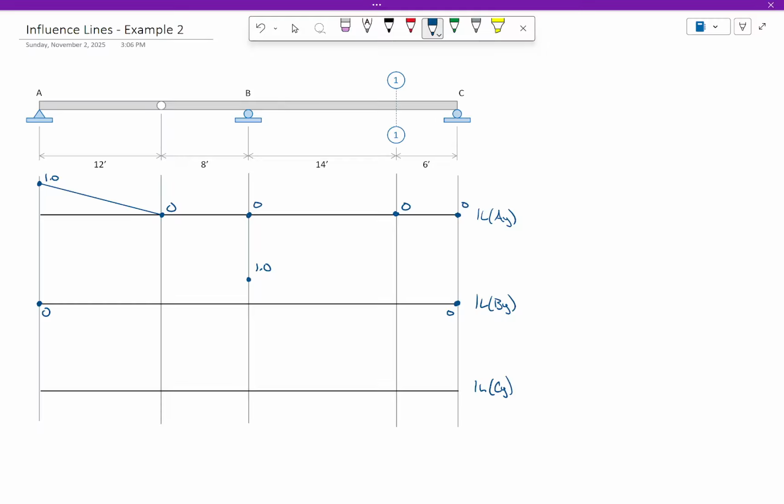Imagine taking that beam and kicking out that middle roller. Now keep in mind, it's still pinned here, it's still pinned here. So I've got to pick this structure up such that that displacement's 1. What does the structure look like? Keep in mind, this is where the hinge is. There are no hinges anywhere else. Start at the hinge and straighten out.